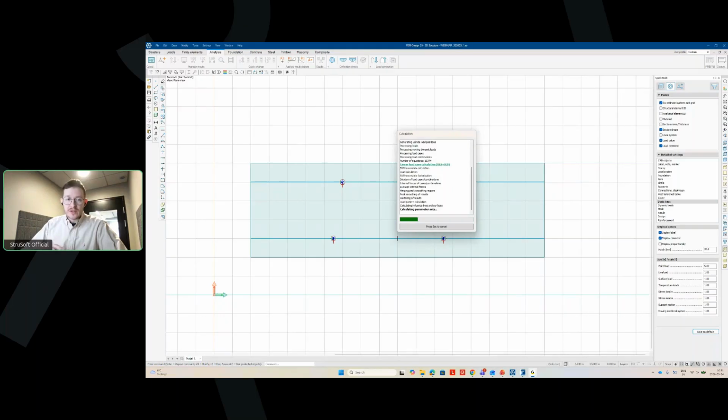And then if you want to create another one, you use the wizard tool. And if you want to create a lot of load cases at once, or a lot of different results for moments and forces and reactions and so on, then you should use the mass generation tool, which I will go through in just a bit here.